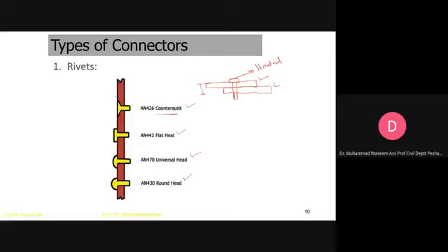When you drive this rivet into the plate, this portion is flattened with the help of a gun, so it is converted to this shape while it is still hot. When it starts cooling, it will shrink, and when it shrinks, it will apply clamping force on these surfaces. These clamping forces are responsible for holding together these two plates. Is that clear to you now?